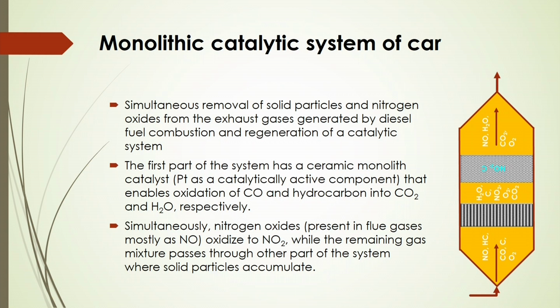So, it is to be remembered that there are two parts of this catalytic converter, where in the first part the ceramic monolithic catalysts are being used to enable the oxidation of carbon monoxide to carbon dioxide and hydrocarbon to water. And there you will also see simultaneously nitrogen oxides present in the flue gases, mostly as NOx, that is NO, nitric oxide.